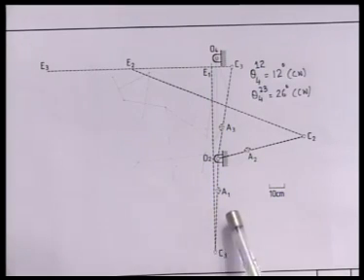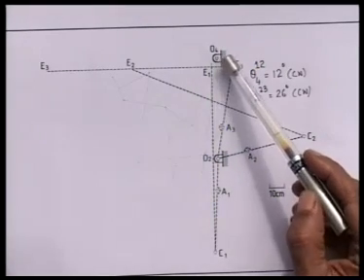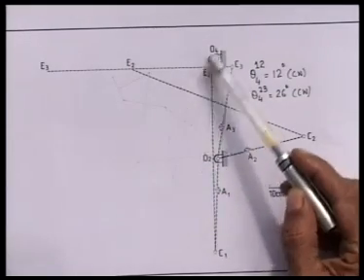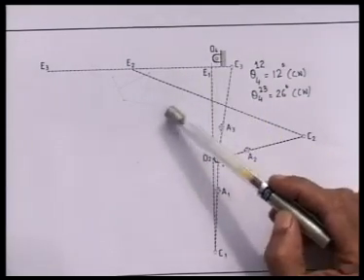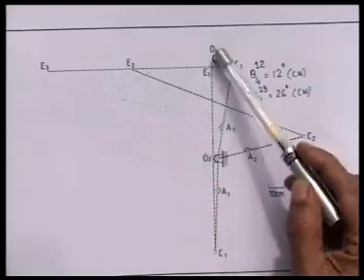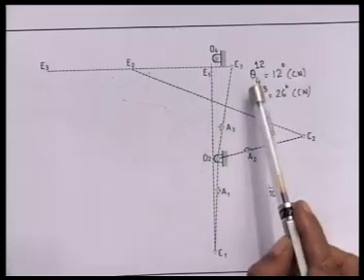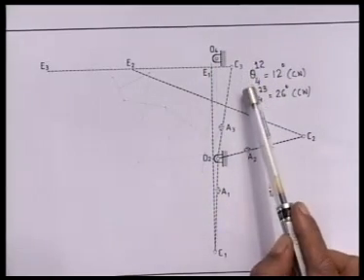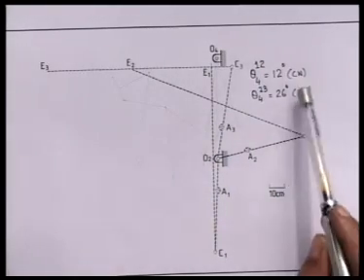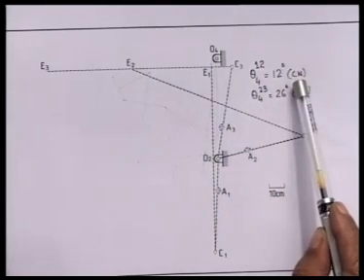It is also specified that the 4th link, which is connected to O4 up to the point B, where there was a second order hinge and 3 links were connected, that point we called B. This O4B is the link 4, and it is also said that the rotation of this 4th link, theta 4 1 2, from configuration 1 to configuration 2 is 12 degree clockwise.